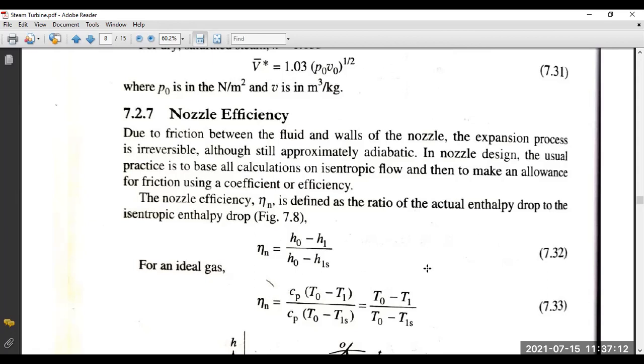Now we are considering the flow of steam through a nozzle itself. A convergent nozzle means the cross-section reduces from the beginning to end at the uniform state. A divergent nozzle is one whose cross-section increases from beginning to end. And a convergent-divergent nozzle is one where first a portion is convergent and the remainder portion is divergent, from which it is exhausted. We also discussed the stagnation pressure of the fluid itself.